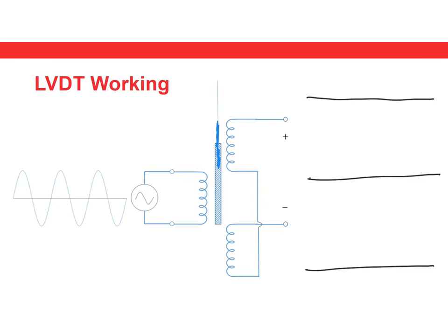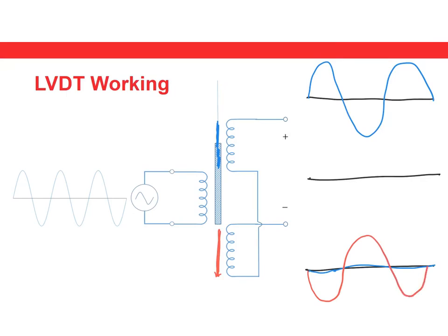What we have is a large voltage on the primary coil, while there is almost no voltage on the secondary coil. But when this plunger is at this position, where almost all the magnetic field goes through this inductor and no magnetic field goes through that inductor, we have a large voltage induced on this inductor, while we have almost no voltage induced on this inductor.